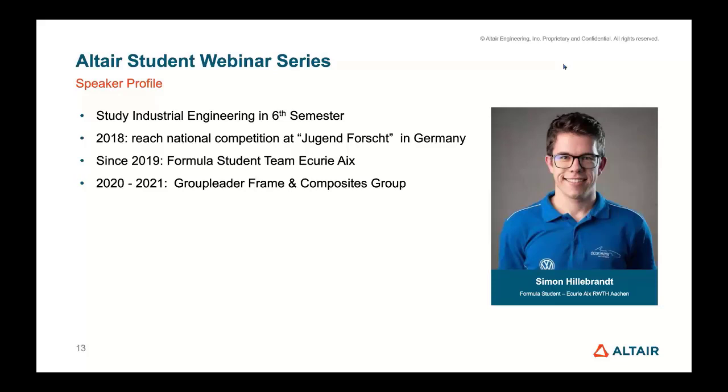So basically you define your material values and then define a failure criterion. You can then, for example, look for Tsai-Wu failure, and you can even program your own failure criteria. So if you have a strain value or a stress value, and your professor or whoever has his own failure criterion, you are able to program that and use it in HyperWorks as your own user-defined failure criterion.